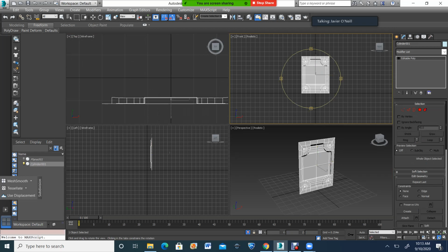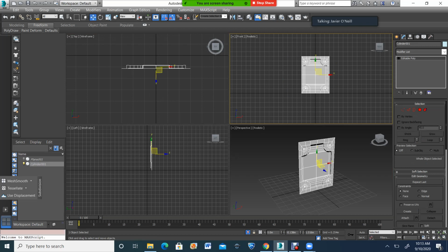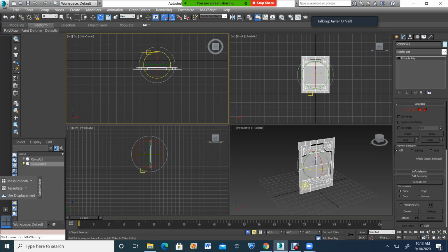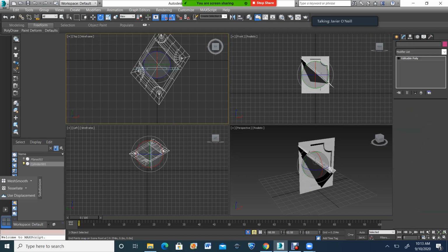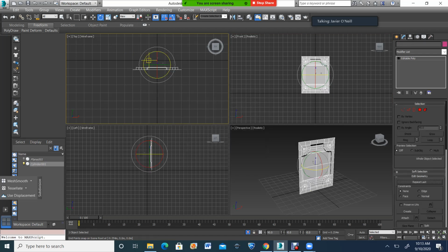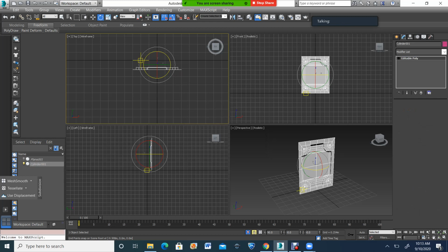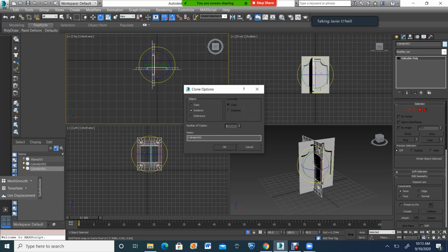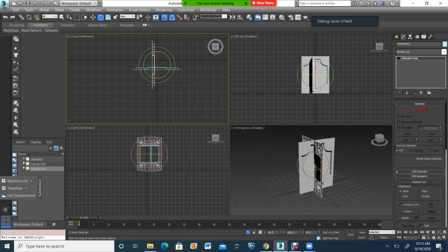So now I am going to take this, it's 1, 2, 3, 6 long. So I'm going to, you know what's easier, just do this. Lock my item, hold shift. Oh, sorry. Hold shift and then make a copy along the axis where it's 90 degrees. That's good. Instance, I want that. And then with snap on to 2.5, I'm going to take this little edge right here.